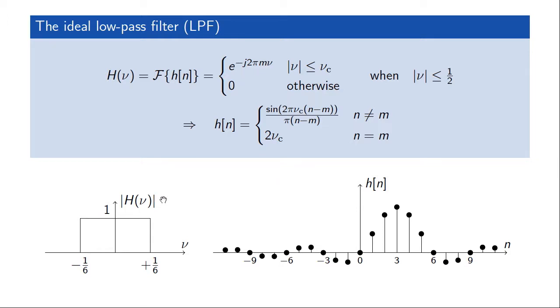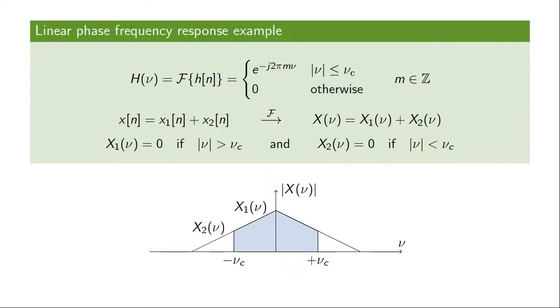So the plot of the absolute value of the transfer function would look exactly the same as before. However, this phase shift here is what corresponds to the shift in time, so it would correspond to a shifted version of the impulse response. And if you look at this phase, it has this particular property, namely that it grows linearly with this normalized frequency. And this is what the linear phase is all about, as linear phases correspond to pure time shifts of the impulse responses or output signals. So let's exemplify that with an example.